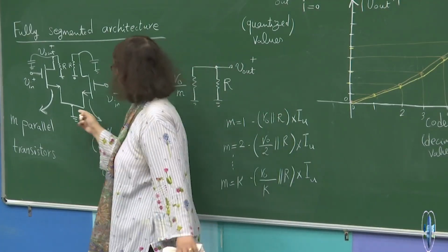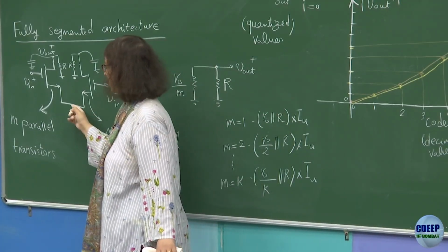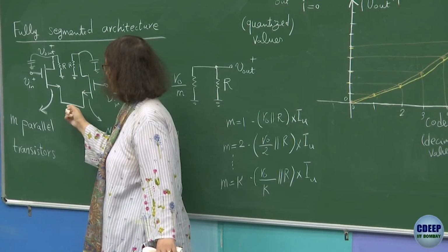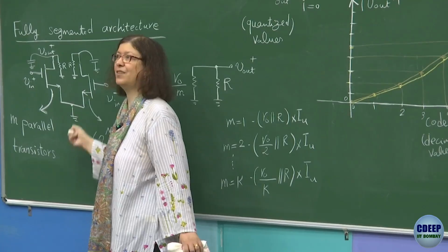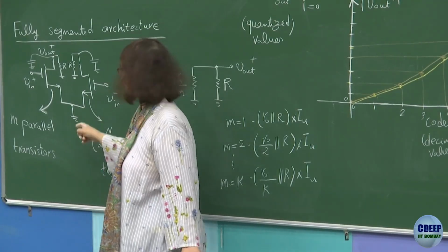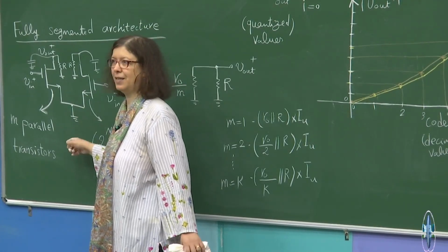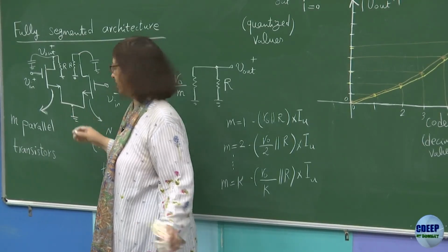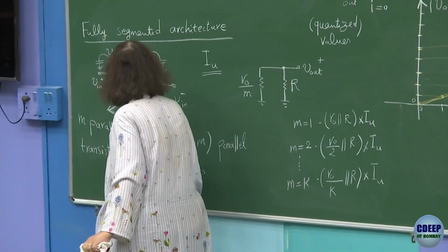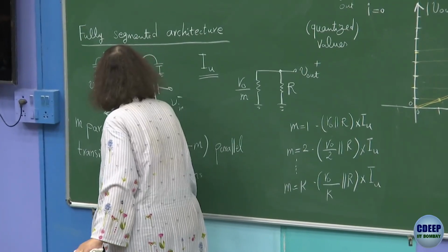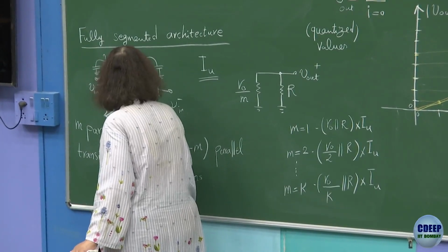Now what will happen when the capacitance at this node increases? Eventually you have perturbation at this node, which will have an impact on the noise of the current source. Because you assume that this current source is an ideal current source, its value is not changing. But actually what you have in differential mode, even in this case, has parasitic capacitors as well.